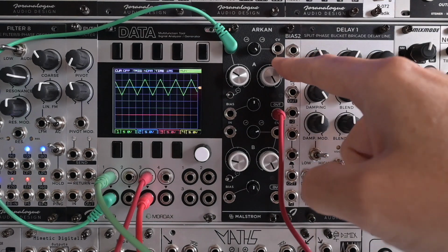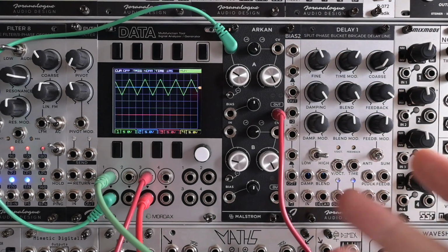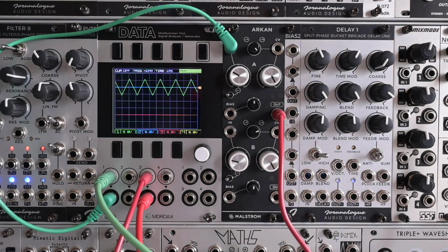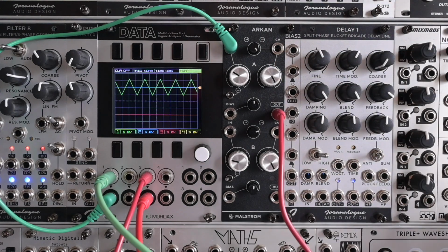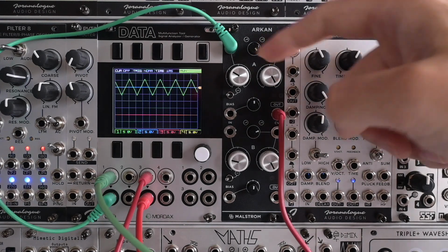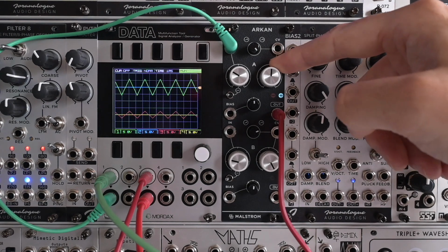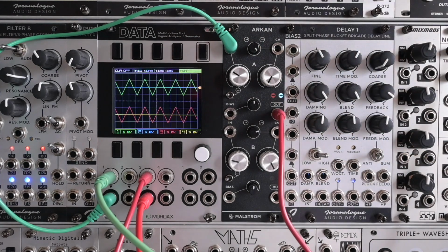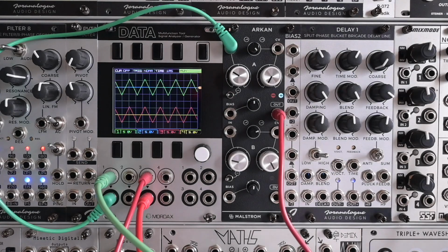And that's right, when there's nothing connected to the CV input here, and this is the CV input where you can patch in your envelopes, for example. When there's nothing patched in here, turning the knob clockwise closes or clamps down the VCA completely. So to get the sound to run through, we need to turn this knob to the left. So let's turn it to the left completely. That means that it's totally open and it lets through whatever is happening at the input stage.